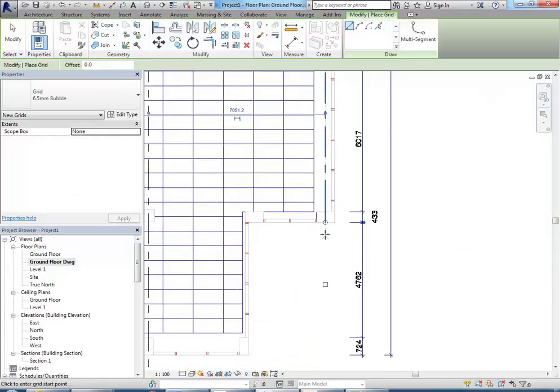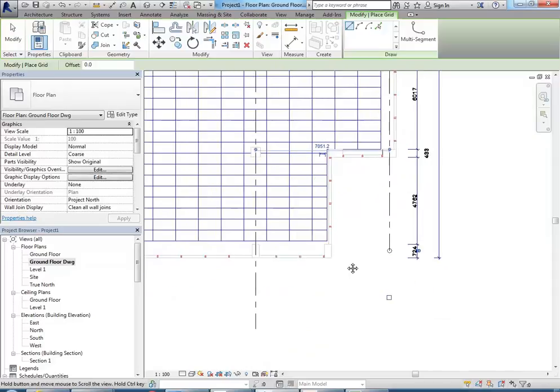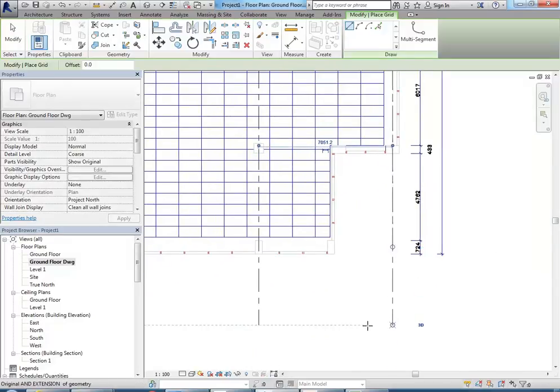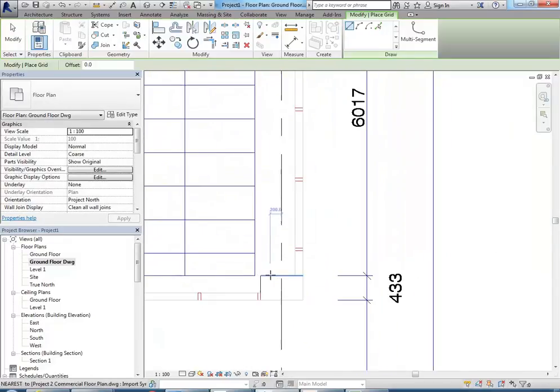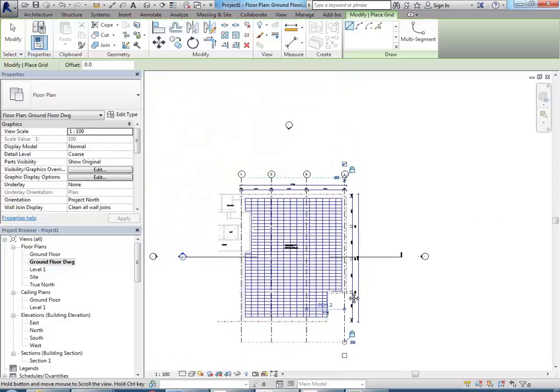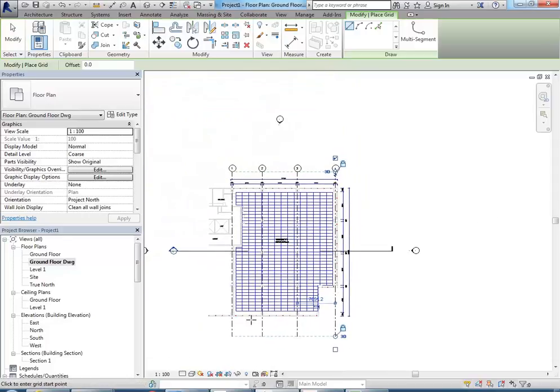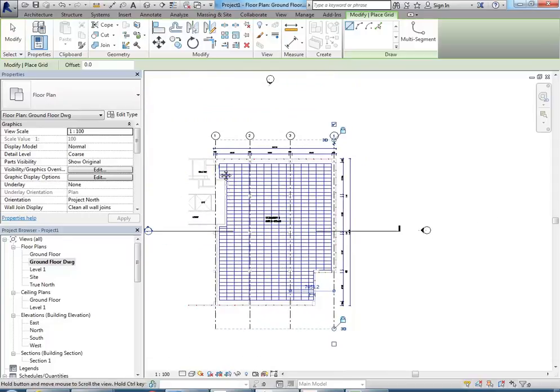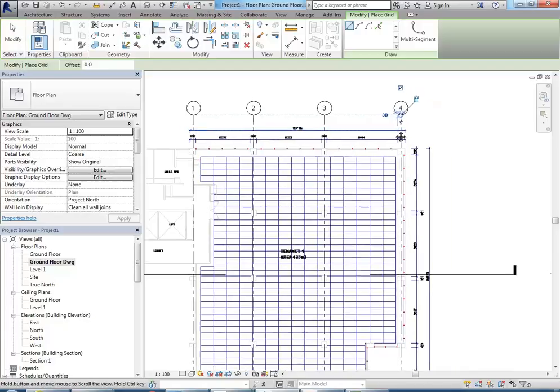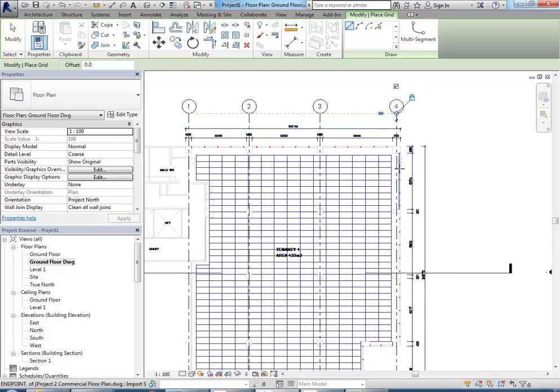Okay, so then it's common practice when you have a grid on the end of the building or the edge to have that grid line aligned with the outside face of the building, but it's not required, and so another option is just to have a different reference, and I'm going to show you how to do that.